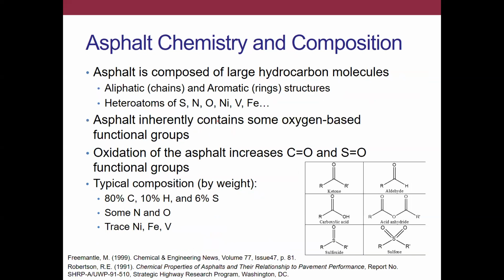So just as a short review on the chemistry of asphalt, it's primarily a hydrocarbon. It does have heteroatoms of various other elements, primarily sulfur, nitrogen, and oxygen. Some nickel, some vanadium, some iron, some other minor amounts, but primarily your asphalt is composed of carbon, hydrogen, and sulfur, right? Those are your bulk majority.